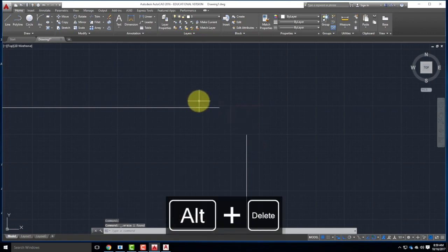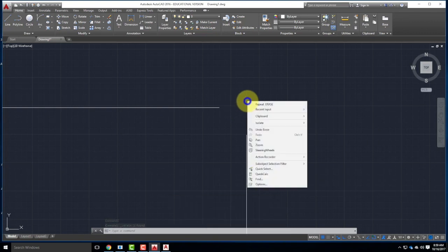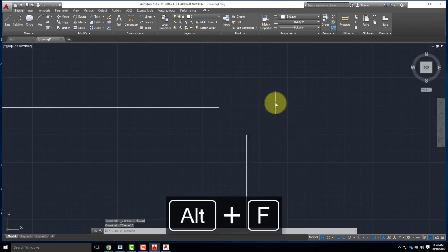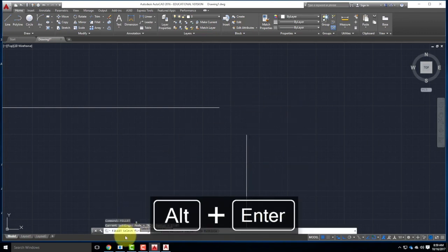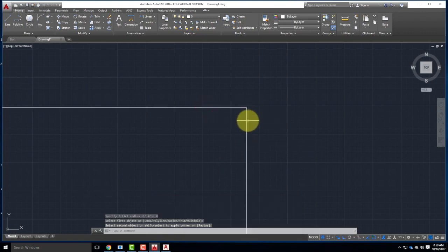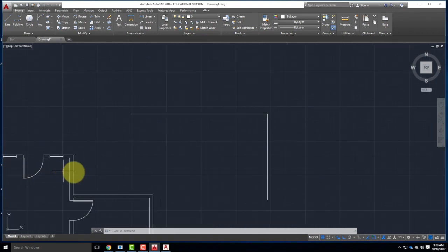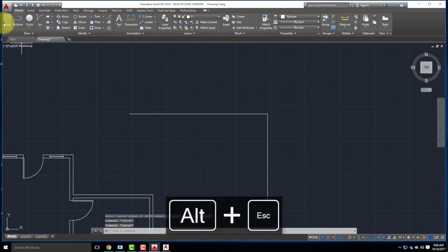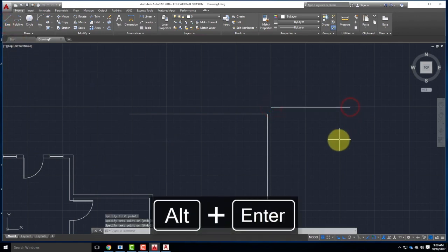If I have two lines in space and I want them to come together at a sharp point, I can use that fillet command. And instead of typing a radius of 1 foot, I'll type a radius of 0. And these two lines will come together at a sharp corner in space. It's a really good trick to be able to work with. There were a couple times where I was drawing over here that I wanted to use that, because that's what I tend to do. Even if you had two lines that were crossed,